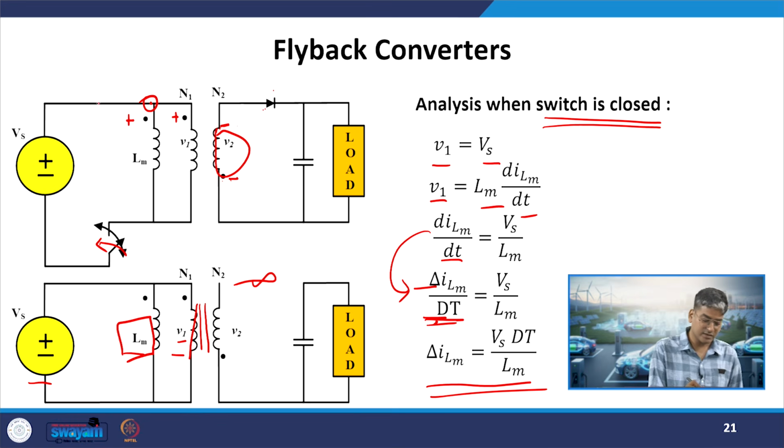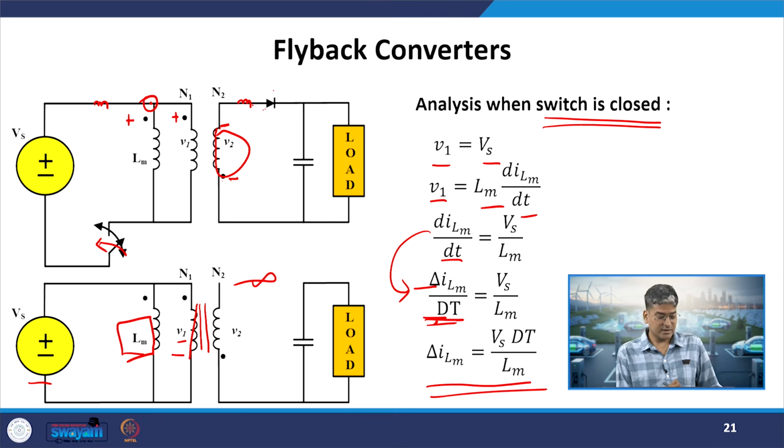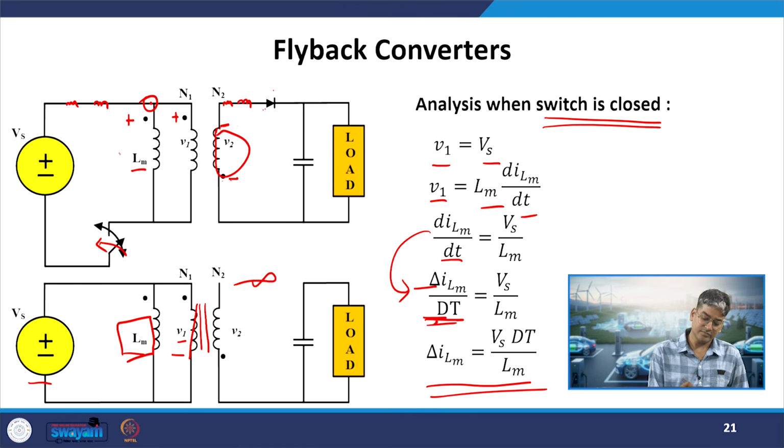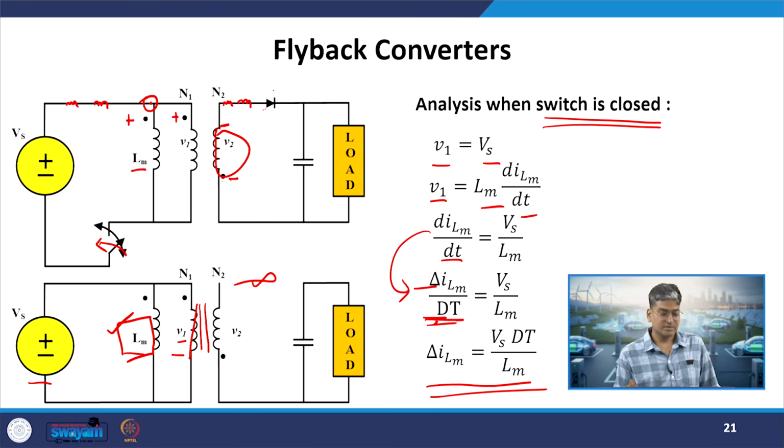And the small inductor value which generates this small amount of flux lines is called the leakage inductance. The transformer wires are constructed using copper wires, so they will have a small amount of resistance. That comes in series, which denotes the winding resistance, or the resistance of the wire used to construct the transformer. And on the core side, we will have Lm and Rm. For simplicity, we have neglected all other components. We are just considering the magnetizing inductor of the transformer, which is represented as Lm.